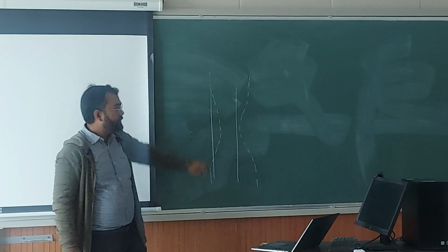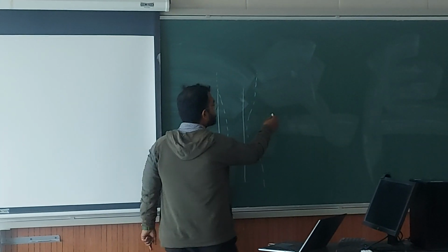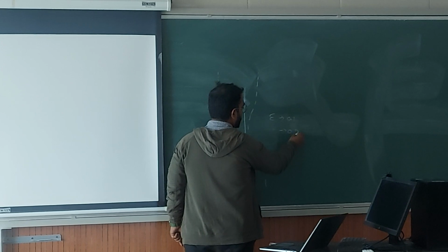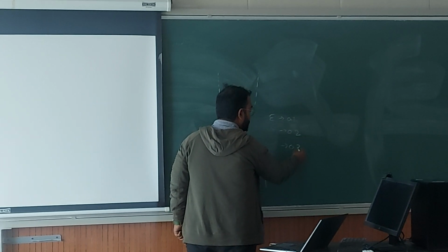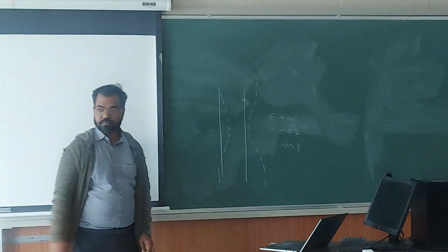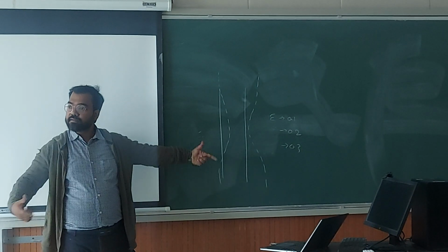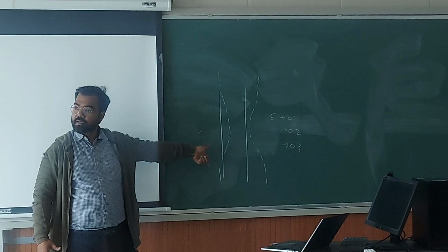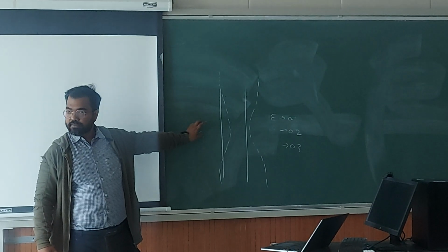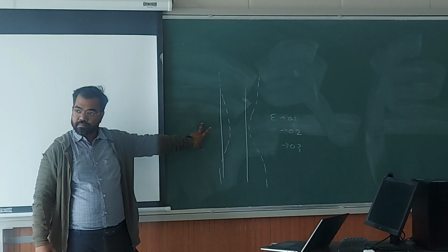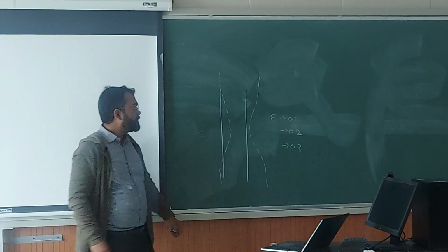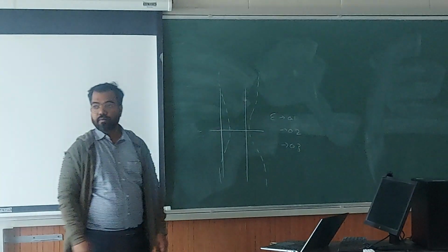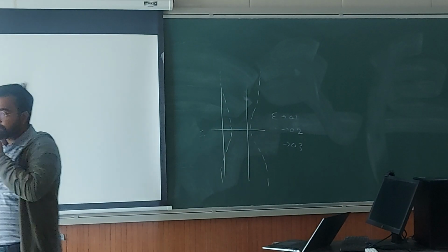One is that you take a tensile sample and stretch it to different values of strain, 0.3 and so on. So you take 10 different tensile specimens. One you stretch to 0.1 and stop the test. Second 0.2, stop the test, and so on. Okay? And then you dissect it at the center and you look at the voids.